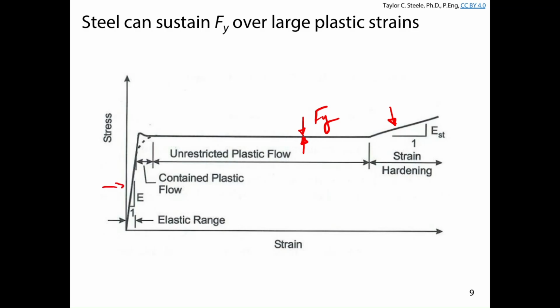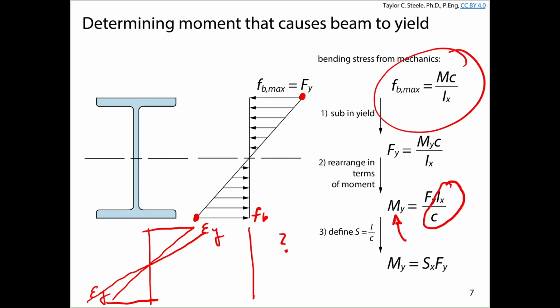And close to the neutral axis, where the strains are still relatively low, we may still be within the elastic region. And so the question is, if for the strain diagram that looks something like this, basically we come down and say, okay, in the regions where the strain exceeds the yield strain, the stress in that region is going to be mostly constant, and it's going to be equal to Fy.